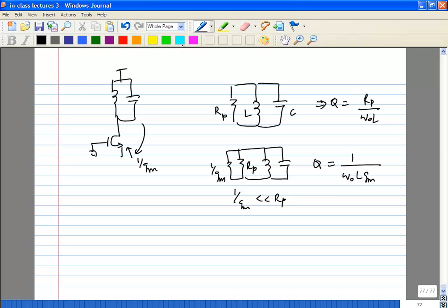So you are designing an inductor for a particular Q. When you stick it in the circuit, the actual Q which it faces may be much less, depending on the impedances presented to it by the rest of the circuit. That's called the loaded Q. So you want to prevent this. So you take this and do some kind of impedance transformation.